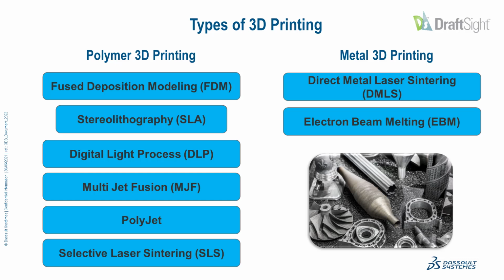The polyjet 3D printing process works very similar to the normal inkjet printing. The process consists of placing droplets of a photopolymer onto the build plate. A UV light then passes over this layer and solidifies it. The process repeats until a part is complete.